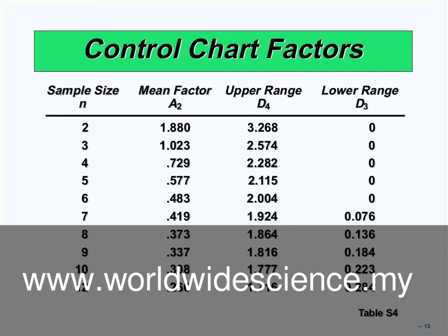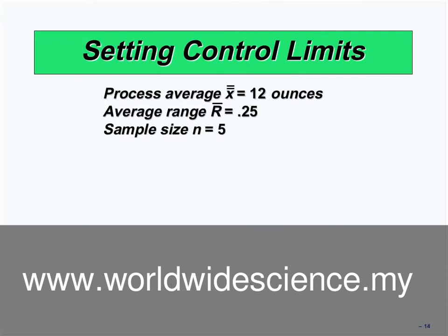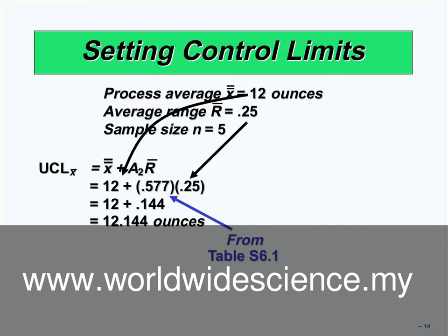The R bar is the mean of these ranges. If you sum the ranges of all 12 hours and divide by 12, you can calculate R bar. R bar is the mean of the ranges, and each range in each hour is the maximum minus the minimum.